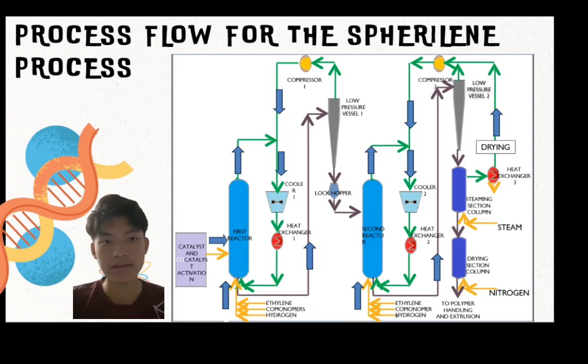The polymer is then discharged to a proprietary unit for final monomer stripping and catalyst deactivation in the spherical product particles. A countercurrent steam flow completely strips off hydrocarbons from the polymer, which are recovered, dried and recycled to the reaction. The wet polymer coming from the steaming section is finally dried by nitrogen in a closed loop system.